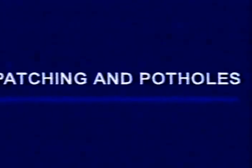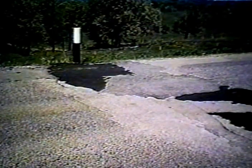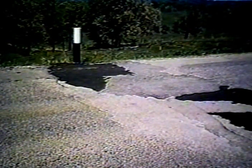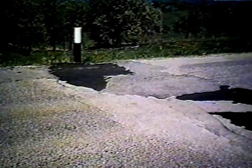Finally, we'd like to move into talking a little bit about patching and potholes. First of all, let's look at this situation. You've got a culvert, obviously, and some settlement over the culvert, and it has been patched. You may also have some frost heave in the winter that leads to the deterioration of the pavement over the culvert. The important thing here is that this is a localized distress. It's caused by the culvert, and we shouldn't interpret this patching area here to mean that you have a pavement problem that extends over the entire pavement surface. It's strictly a localized problem.